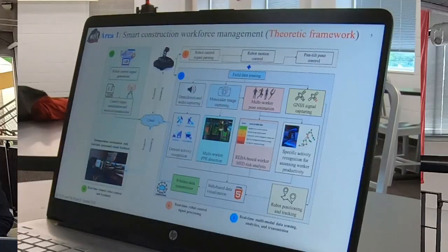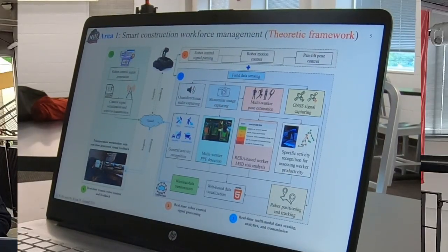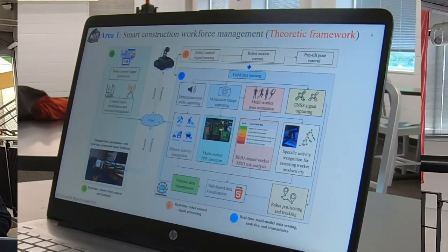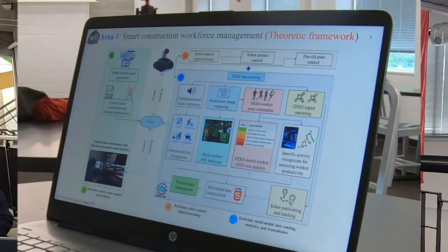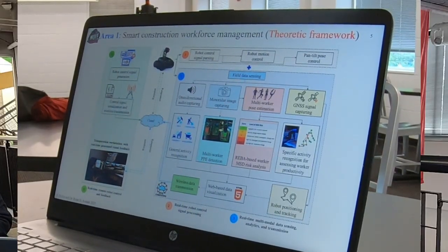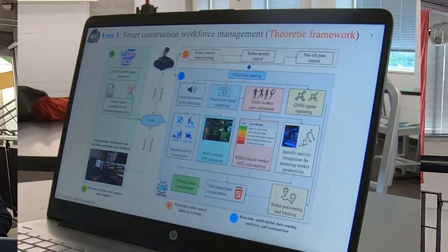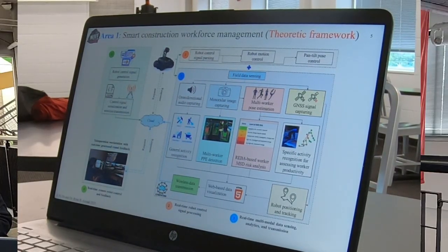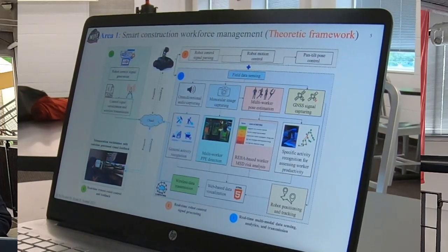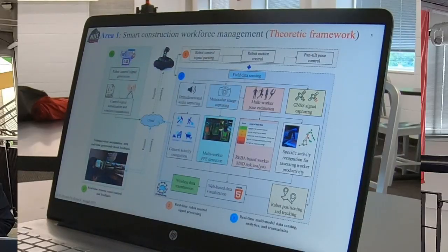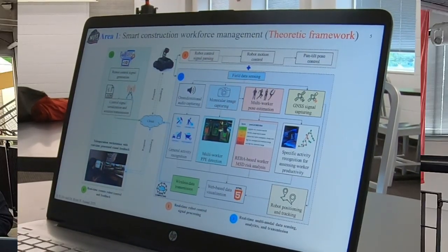And then here shows some hardware setup of this robotic system. Overall there are two things: a teleoperation station on the left-hand side, and a four-wheel driven robot that carries all the needed sensors, the cameras, the mic, as well as the GPS unit I mentioned, and the brain of this robot, which is a high-performance edge computing device. It's called Jetson AGX Xavier because it has very strong computational power. So it's an edge computing device.